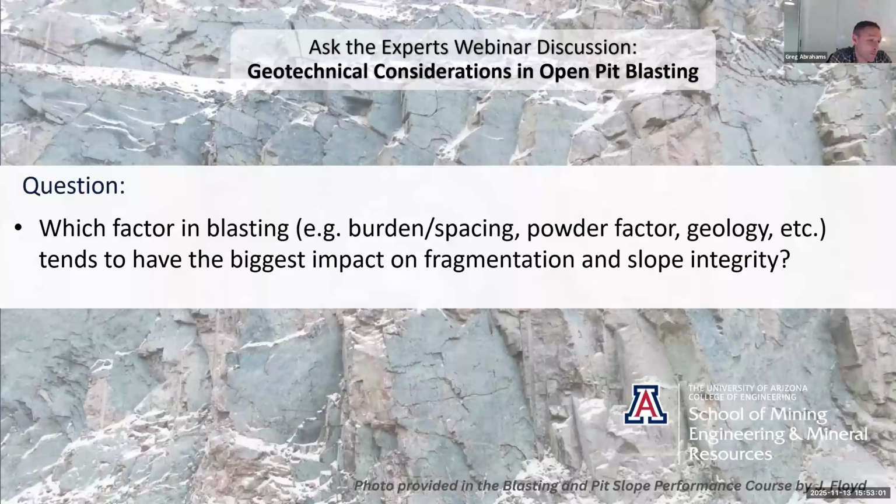All right. Well, luckily, I think we discussed quite a lot of this already. I mean, the immediate answer up front is geology. The geology controls, for me, everything. However, it's the thing that we cannot control. You're given what you're given, and we can control all the other aspects of it: burden, spacing, product, all the rest of it.